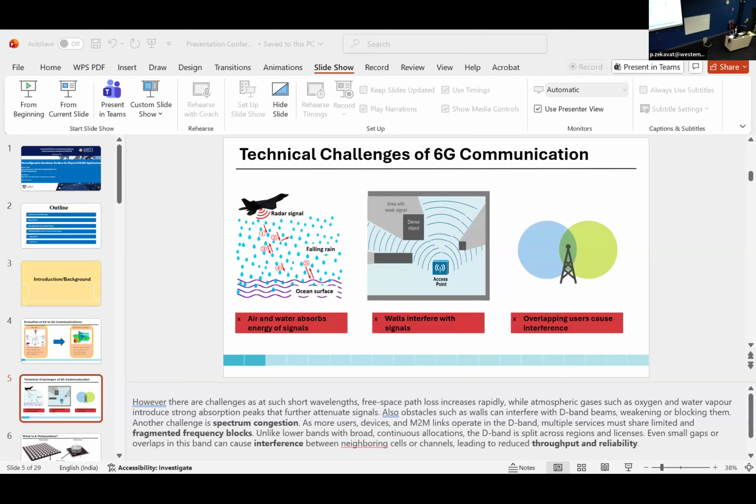And then when the bottom diode was on, this maintained a 33 decibel peak. And then also there was a rejection peak at 33 decibels when the top diodes were on as well. And then the highest rejection peak was when all the diodes were turned on, and this was at 40 decibels. So this shows industry grade shielding performance for the D band electronics in all diode states.